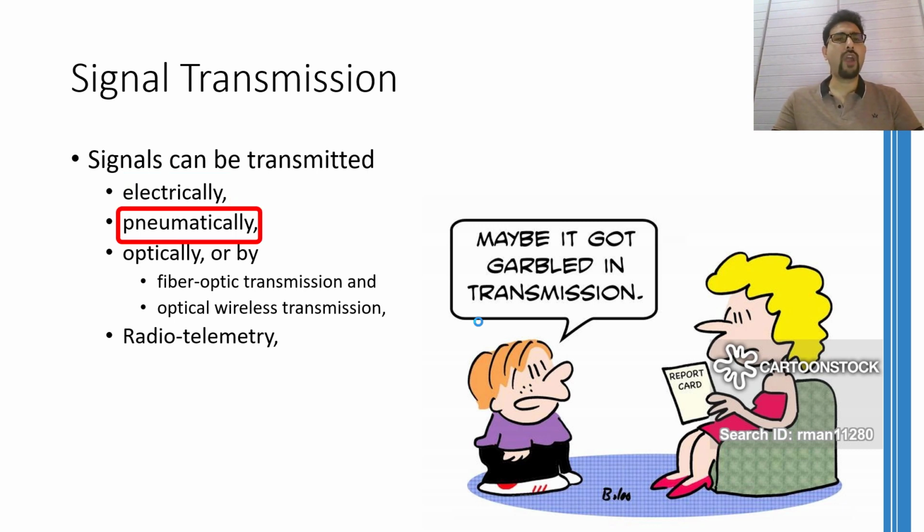The second method is to route the signal using pneumatic means. This method utilizes pressurized air instead of electrons. During your course on basic electric circuits and physics as well, you must have established an understanding that a voltage in an electric circuit is analogous to pressure in a pneumatic circuit. Therefore, if voltage can be used to transfer a signal between two instruments, then why not pressure? Pneumatic systems normally use this pneumatic pressure to transfer information between the two connected instruments.